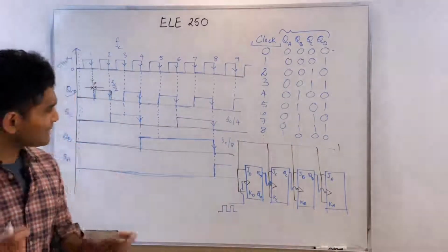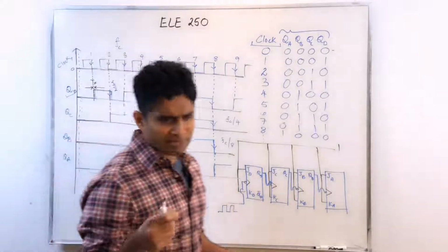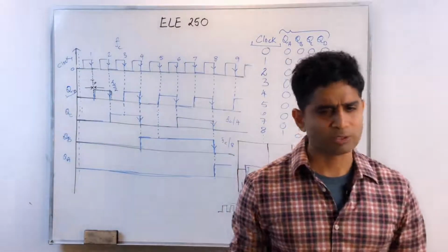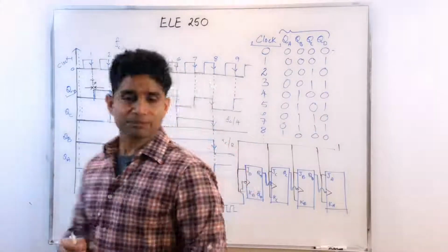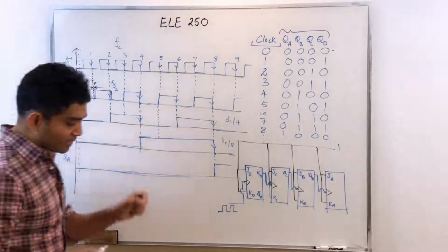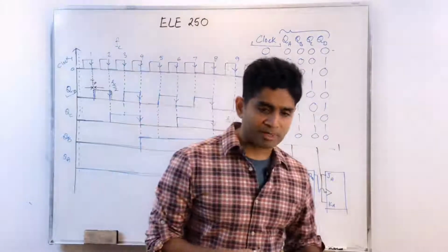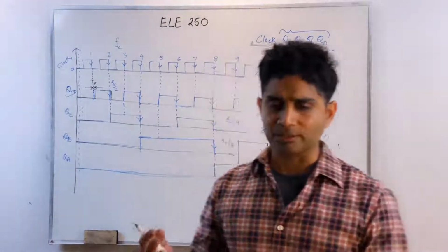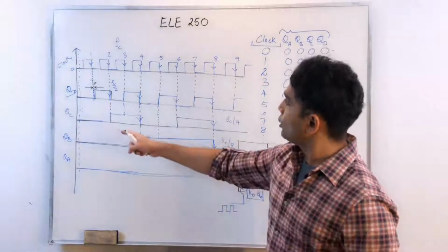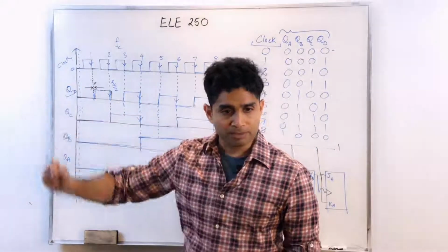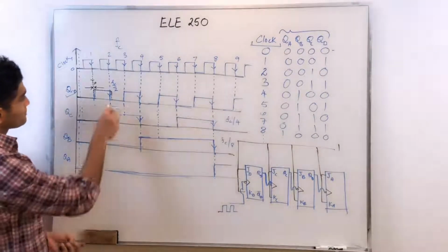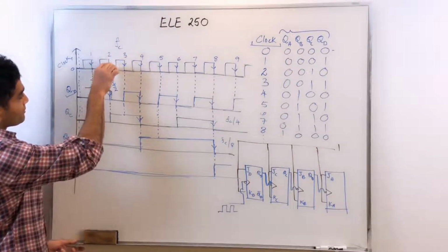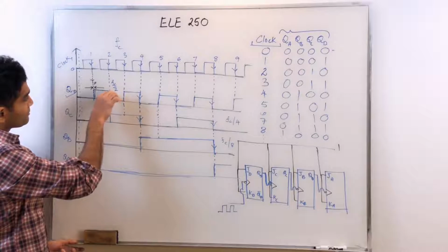If I am using a single flip-flop, it's barely noticeable. You won't even notice it, it's so small. But what happens here? Let's assume that the timing delay is more or less uniform across all the flip-flops. Let's say each flip-flop has a timing delay of TP. For the second flip-flop, QC, the same thing happens.